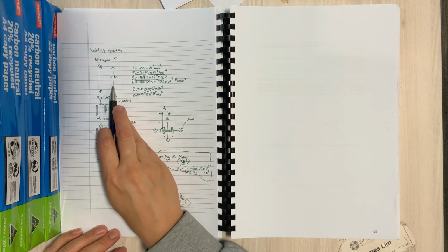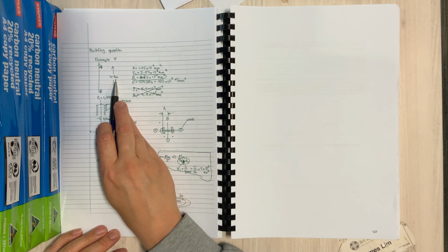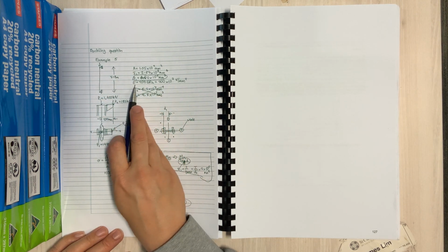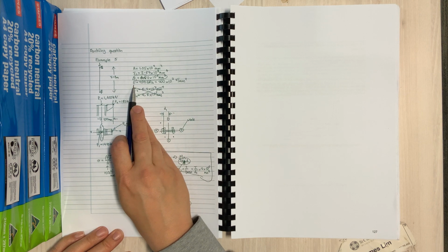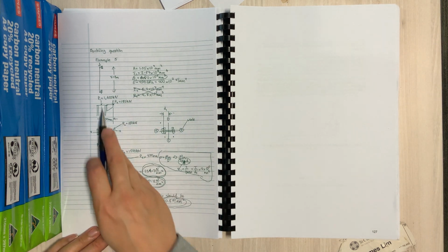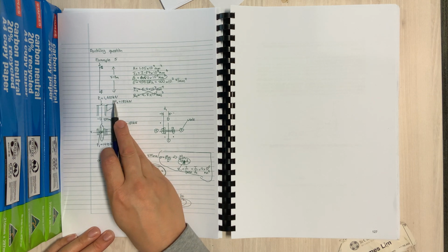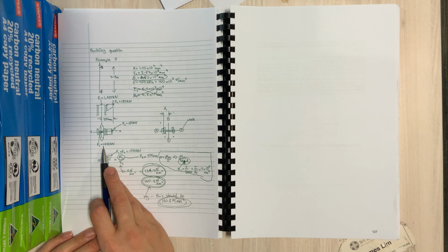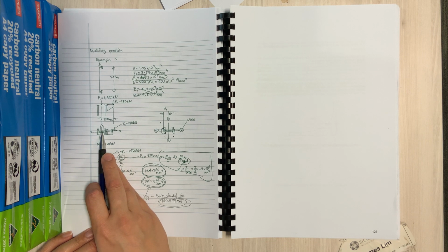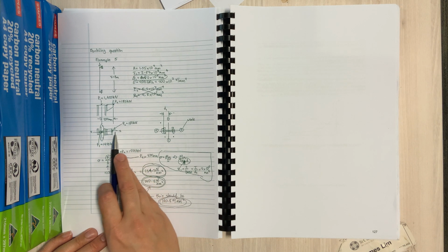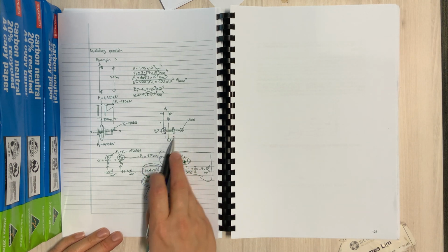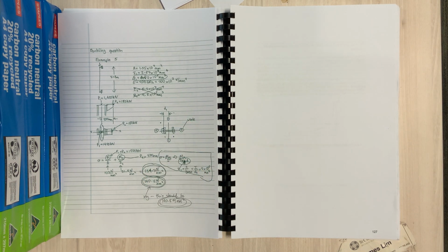So we've got our column, 7.8 meters, pinned at the ends. These are the properties that have been extracted, including the Young's modulus E. You've got the two loads coming down on both sides of the bracket, with the 1420 being applied at the centroid of the I section, and the 180 being applied right at the end. And then here is the explanation for the weak and the strong axis.